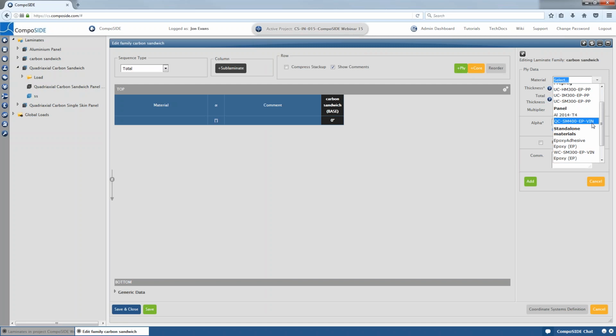I'm going to use quite a bulky ply, so quadriaxial 400, not very optimized, but quite production friendly, pretty easy to lay up and pretty easy to design with. It's fairly as isotropic as composites go, really. So let's add 4 of those plies, and as this is already at 0, plus or minus 45 and 90, I will leave this at the orientation at 0.